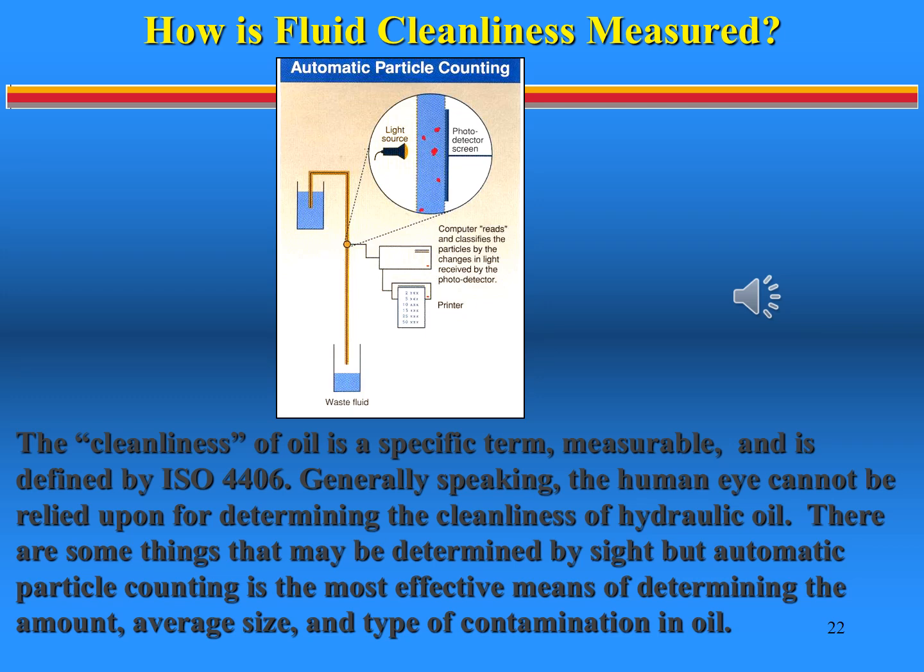Particle counters can determine what the particle is, which in turn can lead to the prevention of a major failure. If, let's say, there are very hard particles of nickel in the oil, this could identify the progress of a bearing failure. Often, the material the contaminant is made of gives a clue as to where it came from.